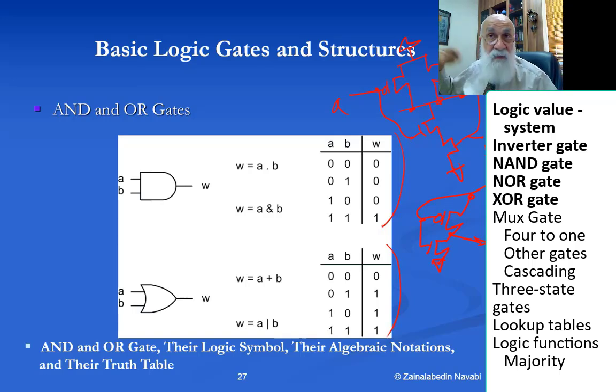And then for ORing, you do a NOR and you put an inverter after it. For the NAND, this is how it's usually drawn. The 2 bubbles next to each other indicate that they cancel out, and the whole thing here is an AND.